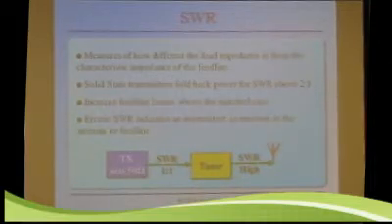Right. Essentially, the whole point is that when the signal's being reflected back, that's bad. You want all the signal going out the antenna. So however much is reflected back is wasted. It's not 100% wasted, but it's largely wasted. It's going to reflect back out, but you lose each time you make that happen. Exactly. And if you have coax, which has very high loss at a high SWR, you're really losing a lot. Whereas if you have ladder line, which has low loss, you're not losing that much.